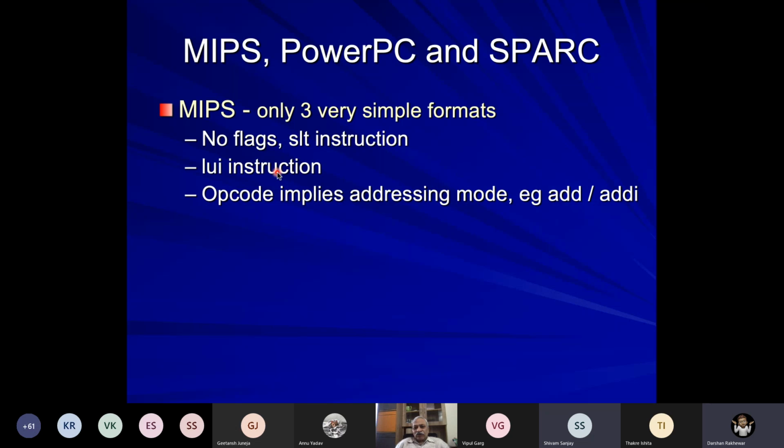When you have instruction of uniform size, one word each, then loading a one word wide address into a register is a problem, because you can't specify that constant address within the instruction. So this processor provides instruction called LUI, load upper immediate. So you load a 16-bit number in upper half of a register. Okay, and then use another instruction to put the lower half. Okay? You can use add instruction or instruction, and that's how you get a 32-bit constant into a register. So two instructions.